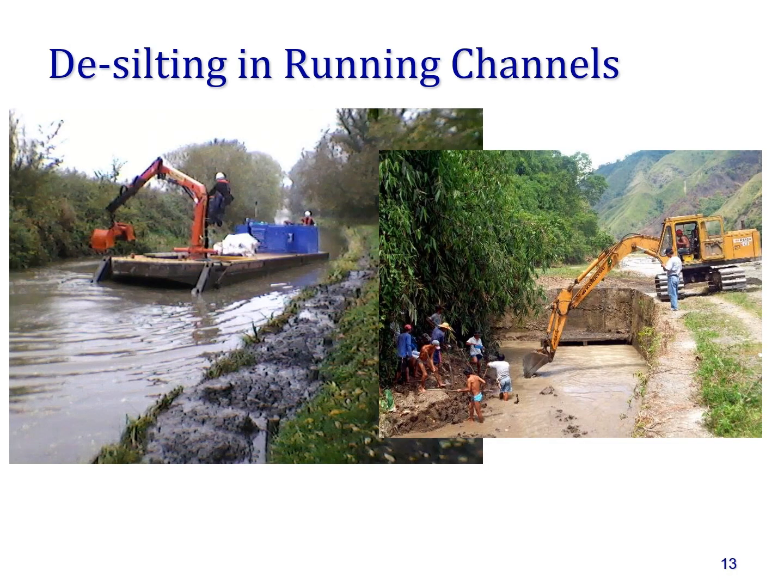This picture shows desilting during the running canal. The same goes here, desilting during the running canal. Some canals have water throughout the year. In such canals, you have to do desilting while the water is running through the canal. You don't have an empty canal because you need water throughout the year in such canals. So this is one example of desilting.